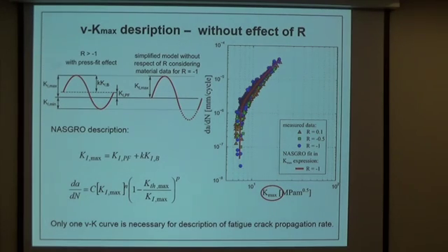So then, for determination of residual fatigue lifetime, we can use just the 1 measured decay curve. So this is an advantage, but we neglect the stress ratio. But as I said, in this case, we assume some imaginary part, so results should be conservative.